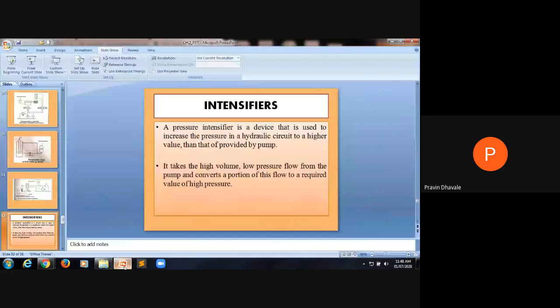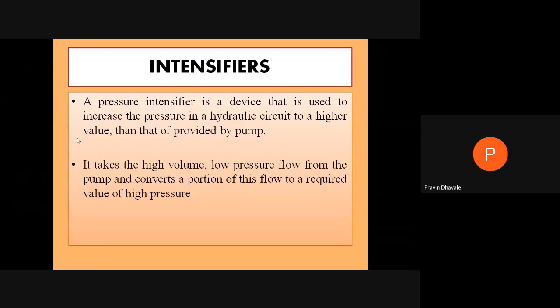The next part is the intensifier. Right. Now, intensifiers are devices called pressure boosting devices. A pressure intensifier is a device that is used to increase the pressure in a hydraulic circuit to a higher value than that provided by the pump.